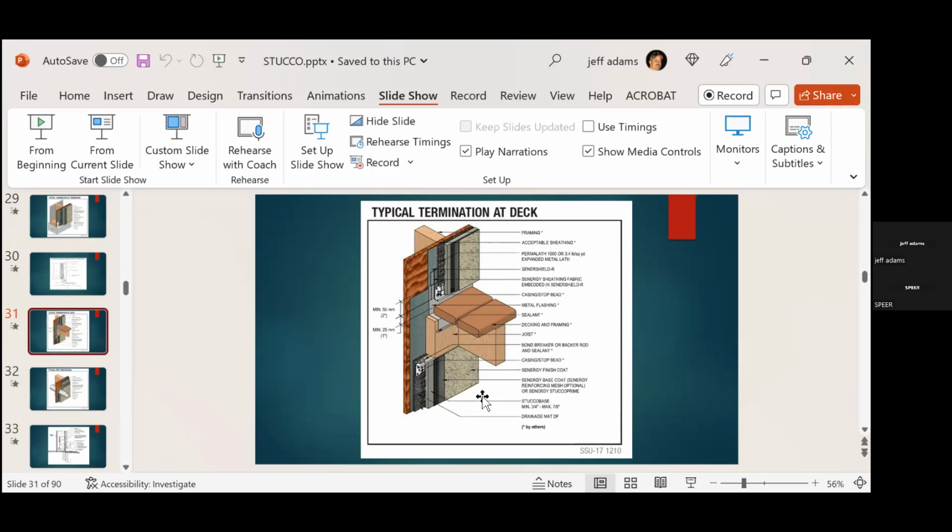We could control that a little bit better, but it does give you an idea of how the deck is supposed to be done with the flashing on top over the ledger and a stop in the stucco. I just did one yesterday for a court case that I just got the documents out last night. Stucco come down, nailed it right through it. Porch roof nailed right through it, all through the stucco. Just huge, massive problems on a brand new house.